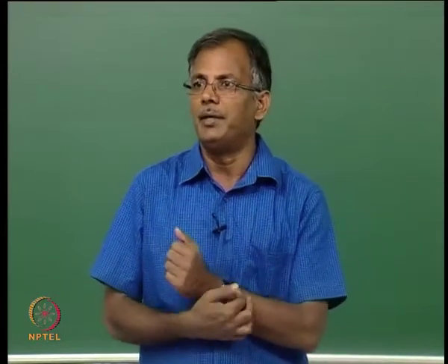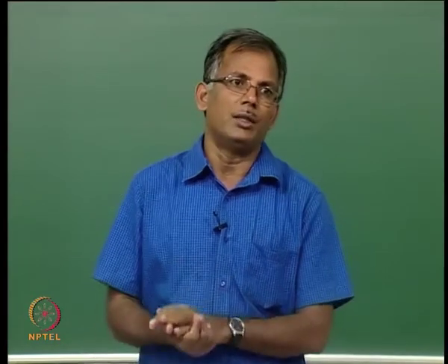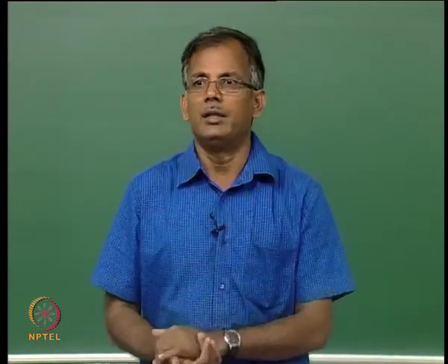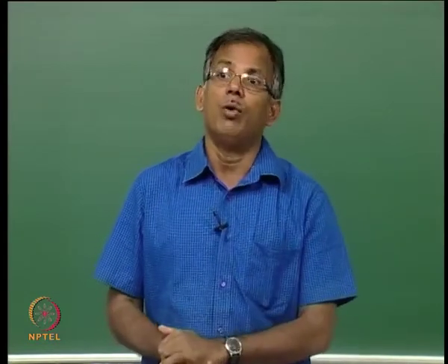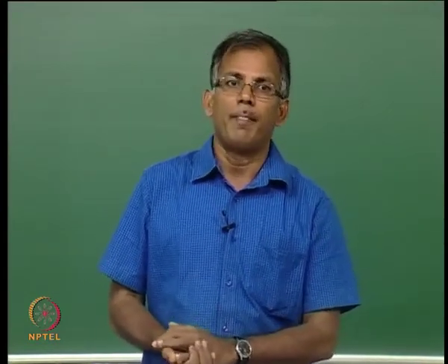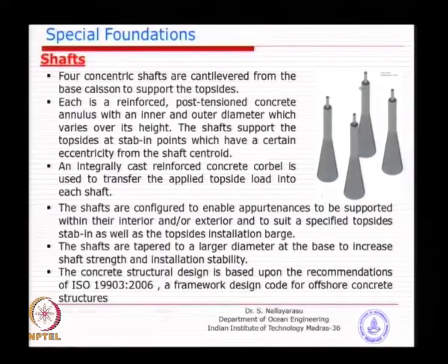So you normally try to taper it in such a way that the wave induced forces are reduced at the top, because you will see that in the top area, from the water surface to 30% of water depth, most of the water particle kinematics will be very high and the loads are very high. So you can design using ISO codes, which is 19903, specifically for concrete based structures.